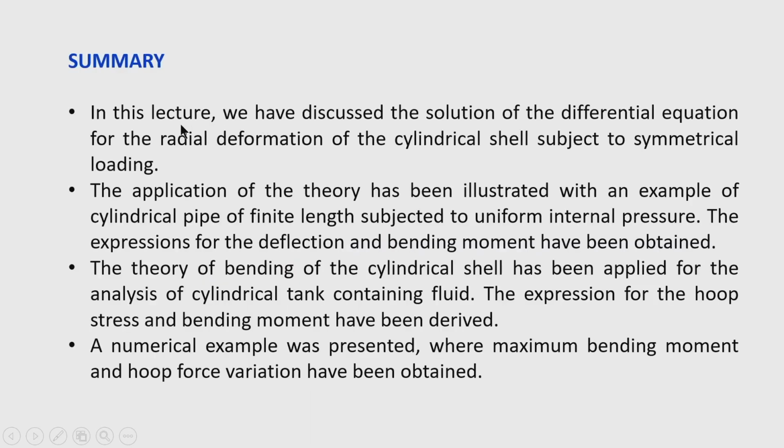Let us summarize today's lecture. In this lecture, we have discussed the solution of the differential equation for the radial deformation of the cylindrical shell subjected to symmetrical loading. The application of the theory has been illustrated with an example of a cylindrical pipe of finite length subjected to internal pressure. The theory of bending of cylindrical shell has been further applied to the analysis of a cylindrical tank containing fluid. Lastly, I have given a numerical example to illustrate the theory. Thank you very much.